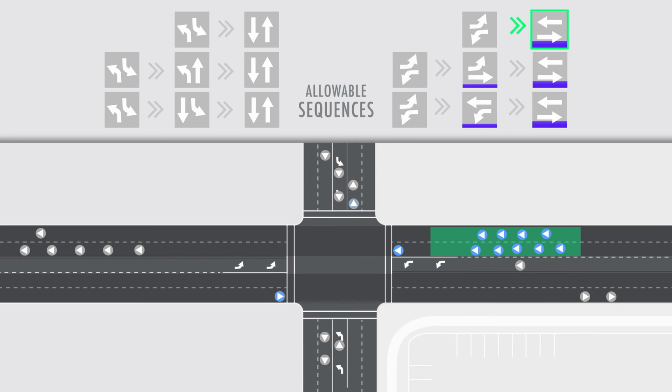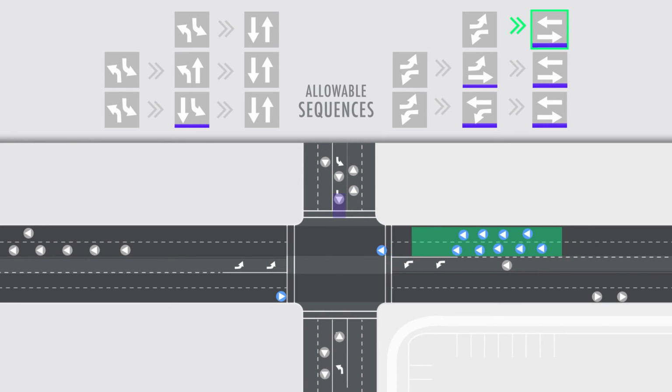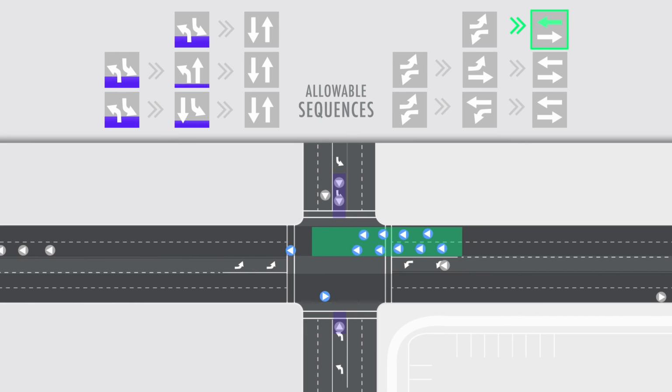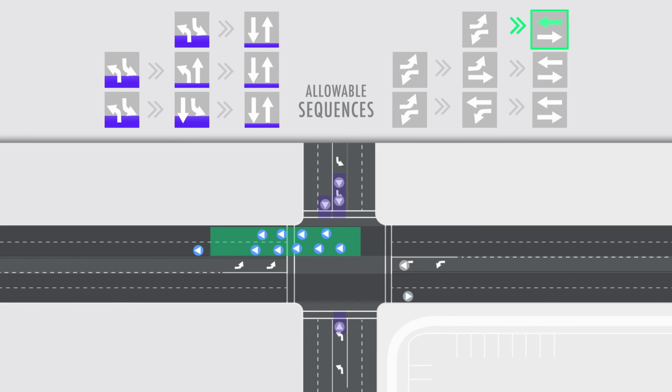When choosing a sequence, InSync evaluates demand as well as the arrival of the green tunnel. InSync sees that a vehicle is waiting in the westbound through and will try to release the through movement with enough time for it to pick up speed so as to not slow down the cars in the approaching green tunnel. The westbound tunnel has been served, but the eastbound tunnel is still coming. InSync knows that it has enough time to reserve a state within that period before the arrival of the eastbound tunnel. InSync chooses to reserve the north-south lefts and the extra time based on demand.